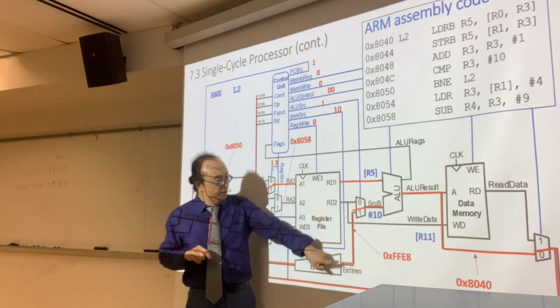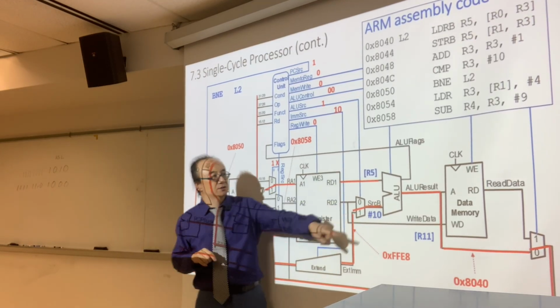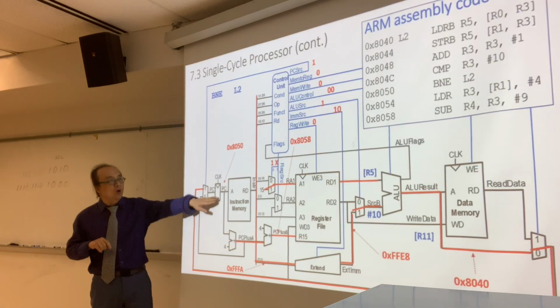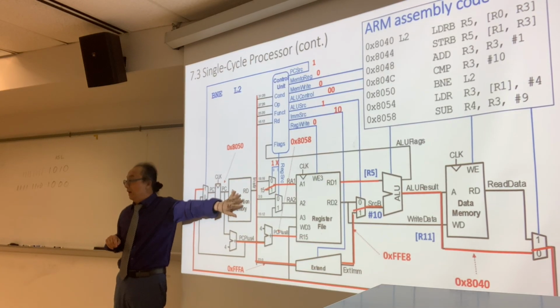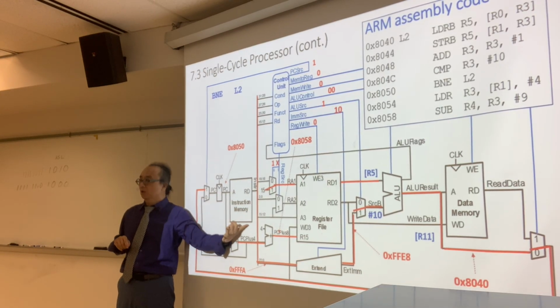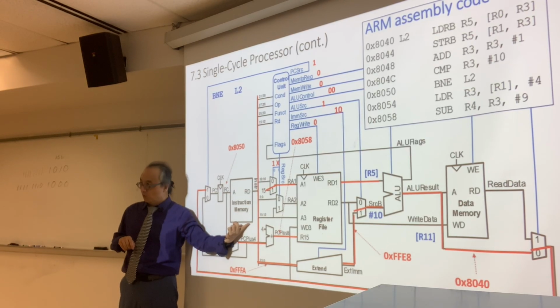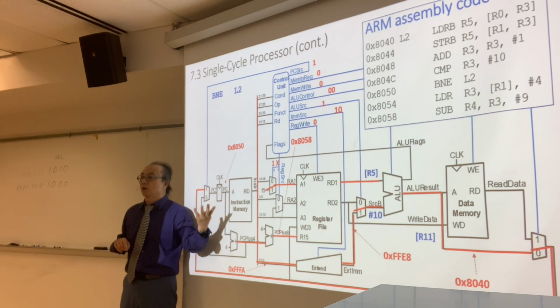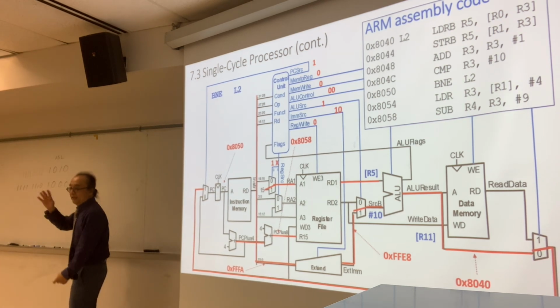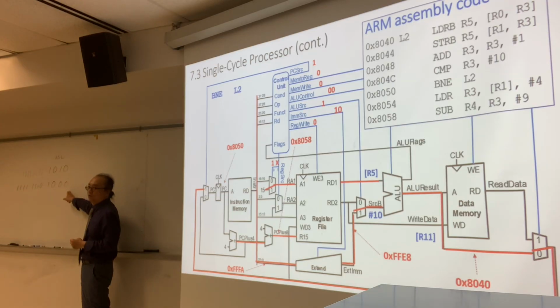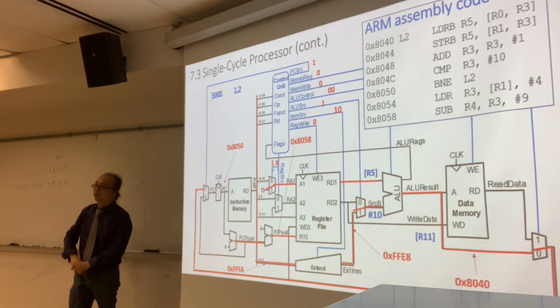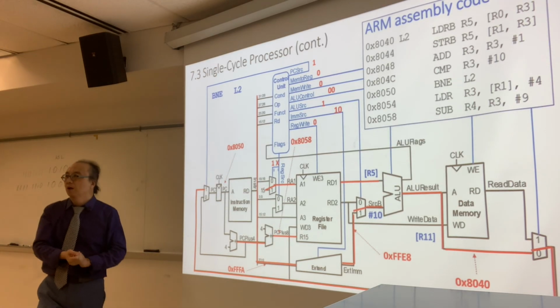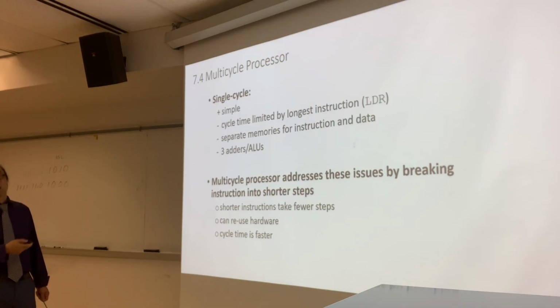By adding this guy plus the content of this is not enough, because all of these instructions are, how long is this guy? 32-bit. How many bytes? 4 bytes. So the address is incremented by 4. So to get into the right instruction, we have to shift left by 2 so that we can get the byte address of that instruction.